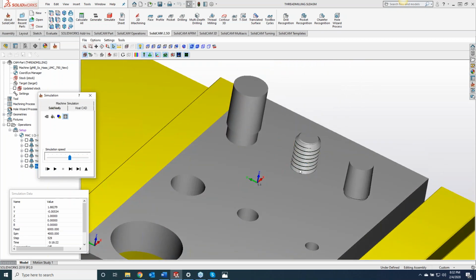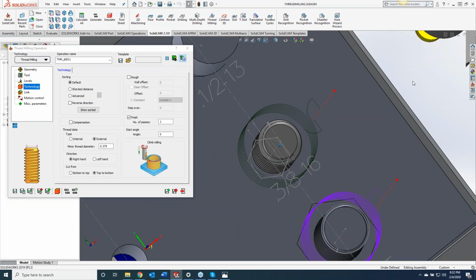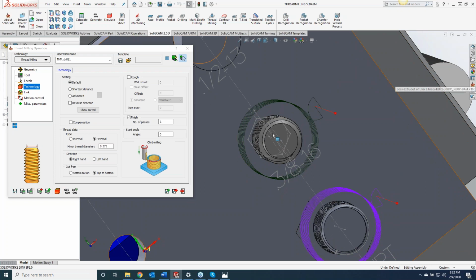So you can see we're going straight down, grabbing those threads, but like I said, it's not showing much action going on there because we're using just a cylinder. Now, like what Greg was saying earlier, if we want to change that clock position or our start angle, we can definitely do that. And we can set it to whatever angle you guys would like to have in there. So you can see that it shifted it over for you.